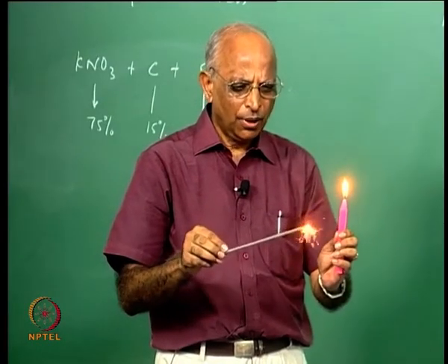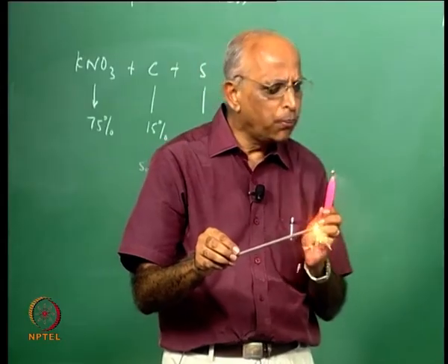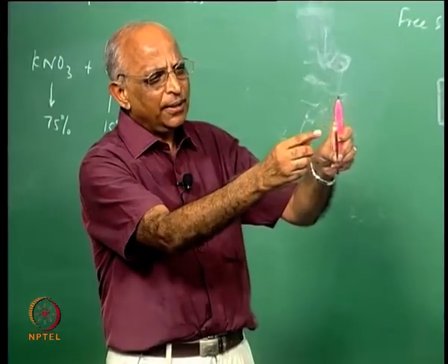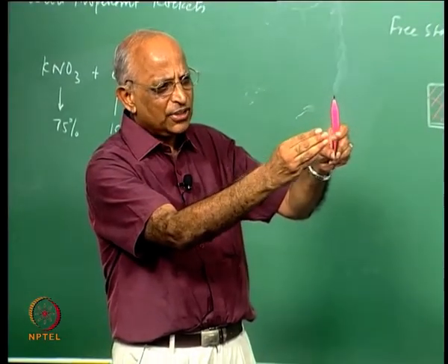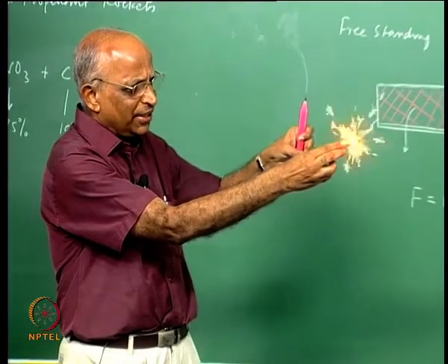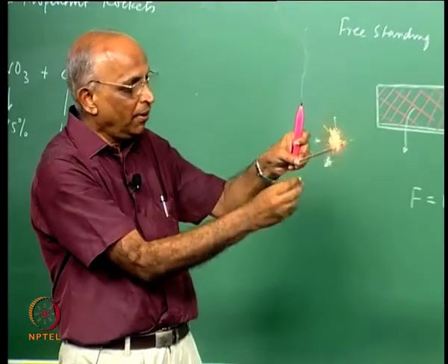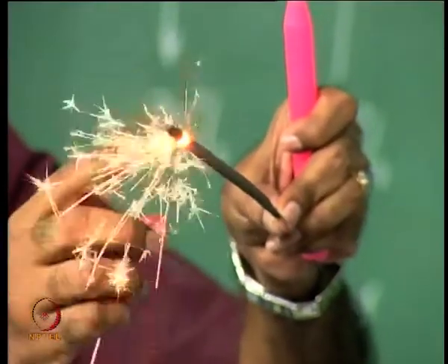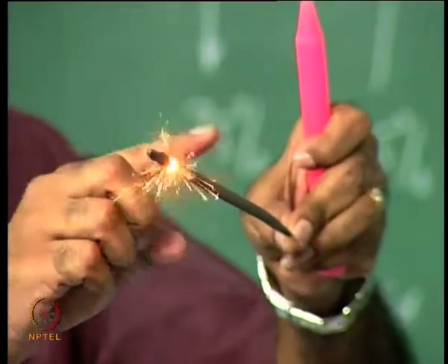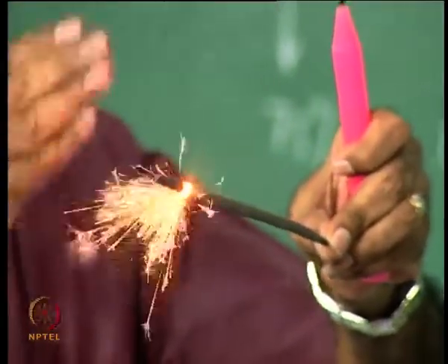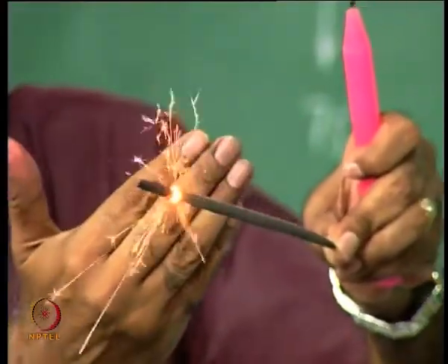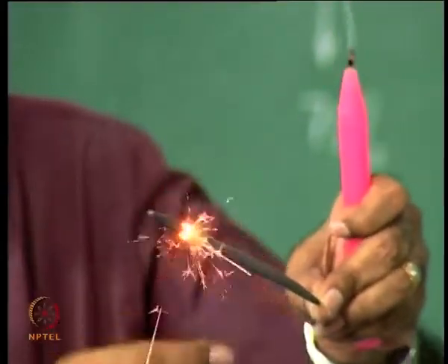See, how does burning take place? You have the surface which gets ignited, and this ignited surface burns the next surface and so on. Therefore, you find that the surface is regressing at a particular rate. Well, in this case the whole surface is exposed, but because it is air over here, the flame expanded, it is not able to ignite the surface. Therefore, the burning surface area is perpendicular to this plane and the burning progresses. This is the case of this composition.